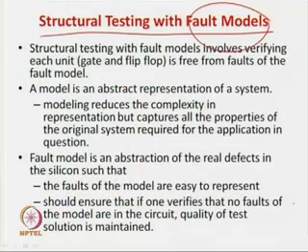We verify whether the AND gate is functionally correct, that is 0 0, 0 1, 1 0, 1 1. And in the case of a full adder, we have to verify whether it is doing the addition, whether sum and carry out are proper or not. But if we go for structural testing with a fault model, we will even forget that an AND gate is an AND gate and a full adder is an adder.